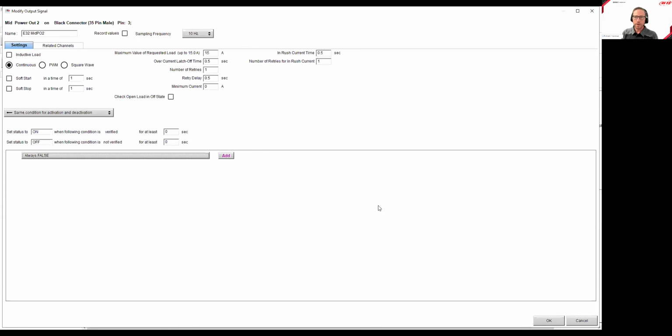So, automation. We touched on it a little bit, but I really enjoy the automation aspect of the PDM. I can say, okay, I want to turn my fan on if engine coolant temperature is above 170 degrees. I'm going to start my cooling cycles and turn things on, turn things off. Now, I always program in an override.